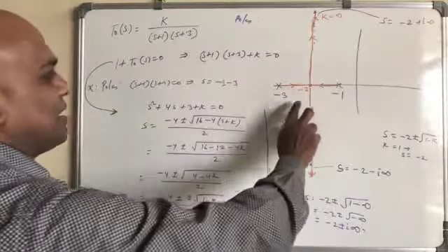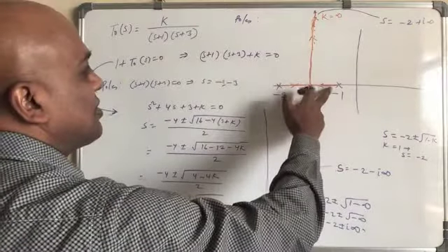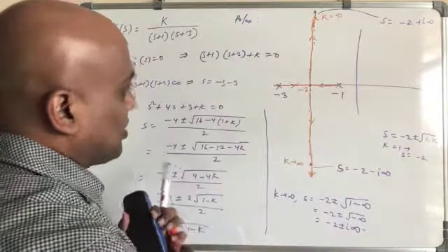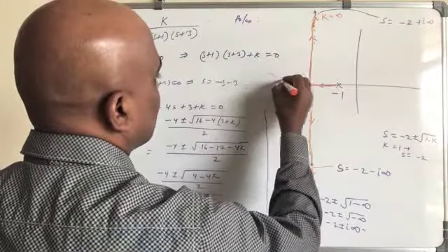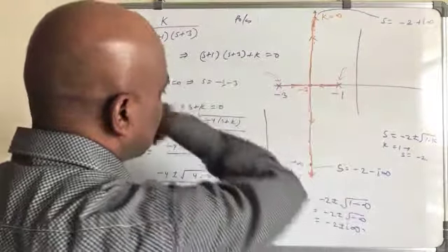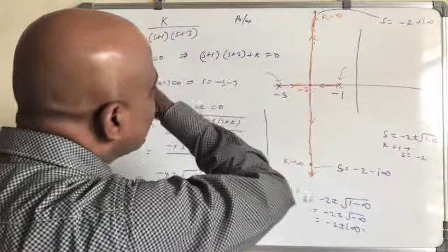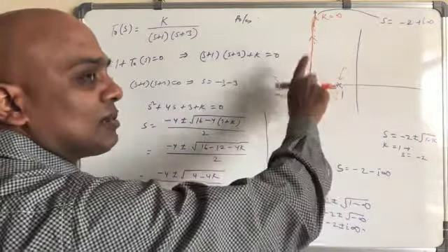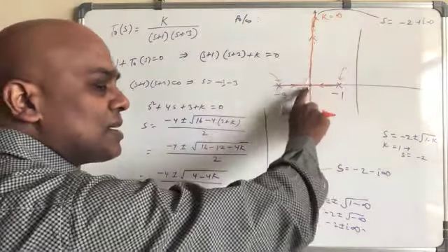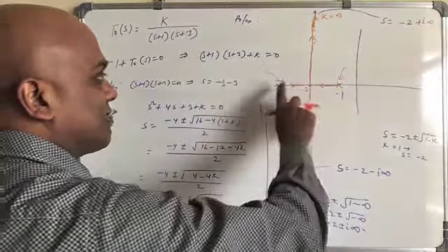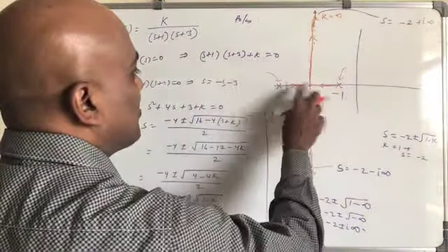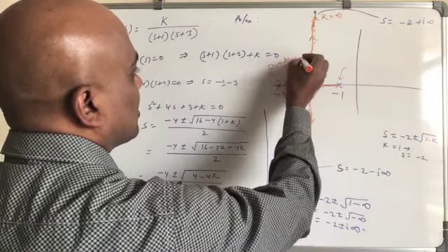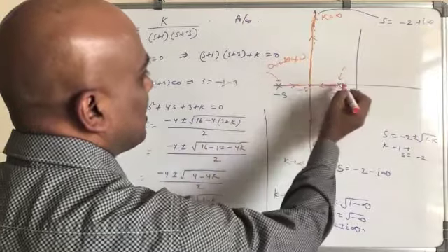What you see here is that if k equals 0, it is an overdamped system. You have both the roots real in this case. What you are plotting as a function of k is the roots of the characteristic equation of the closed loop system. So these points are overdamped system here and here.